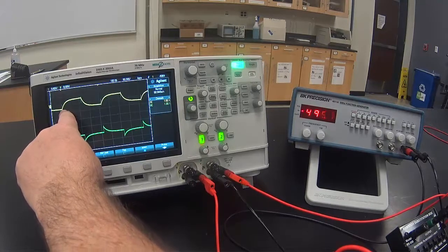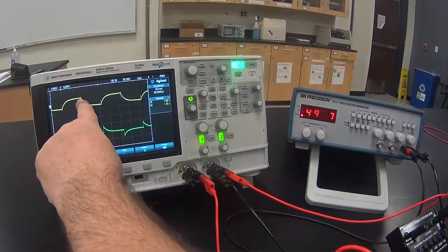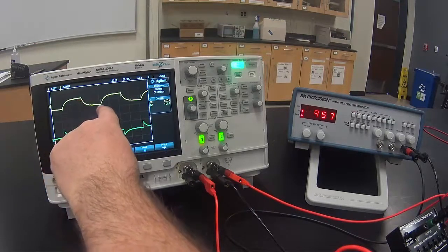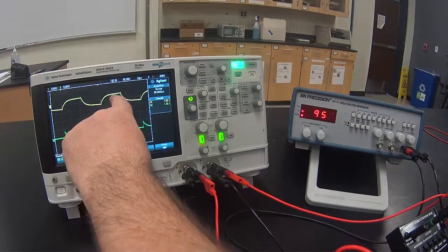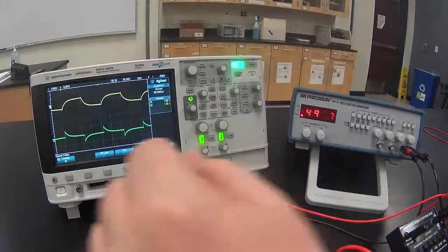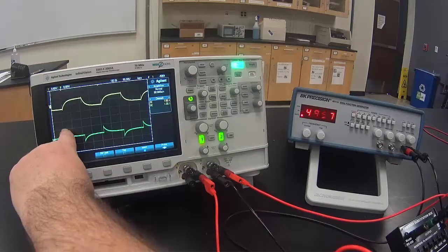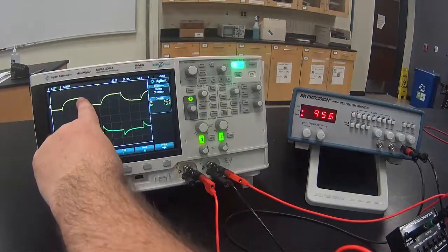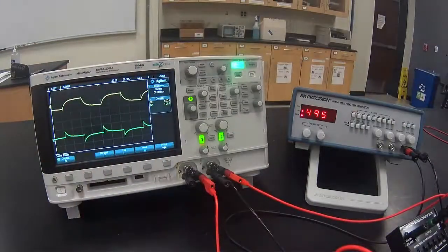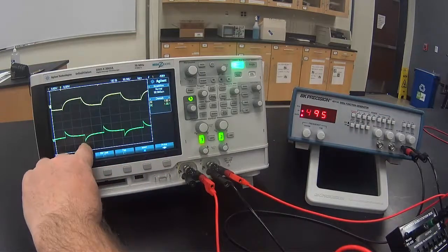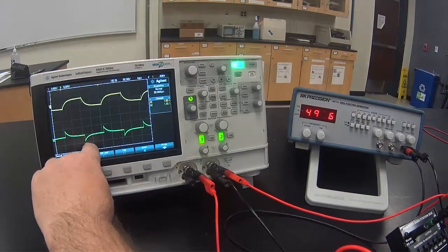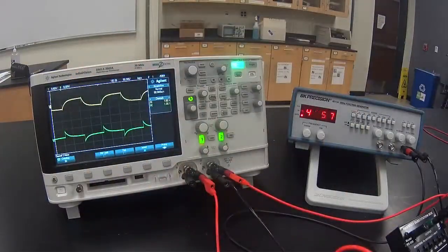So we look over here, we see the capacitor charge, then discharge, then charge, then discharge. The resistor voltage goes really high when the capacitor first starts charging and then goes back to 0. So once the capacitor is fully charged, there's no current flowing. Then when the capacitor starts discharging, the voltage goes really high in the other direction. But as it discharges, it goes back to 0 current once the capacitor is fully discharged.